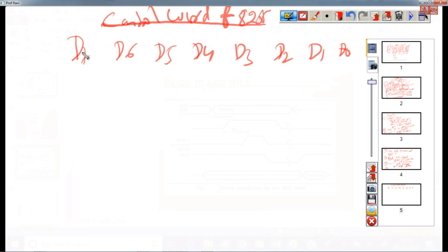So we are using 8255 in simple input output mode, not BSR mode here. So this should be 1. And we are using mode 0, input or output. So this is group A. Group A means port A and all. So this is 0 0 for mode 0. And D4 is port A. Port A we are using as an input port.